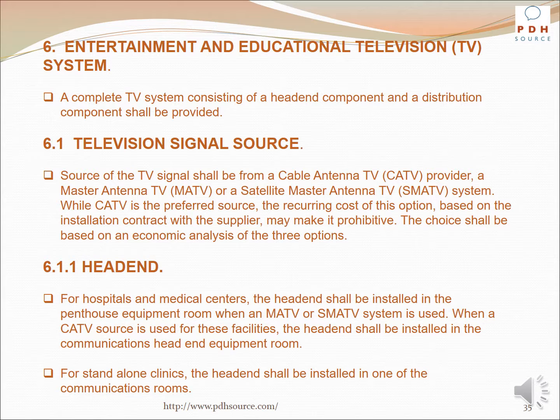For hospitals and medical centers, the head end shall be installed in the penthouse equipment room when an MATV or SMATV system is used. When a CATV source is used for these facilities, the head end shall be installed in the communications head end equipment room. For standalone clinics, the head end shall be installed in one of the communications rooms.